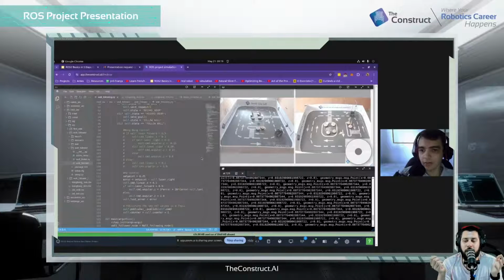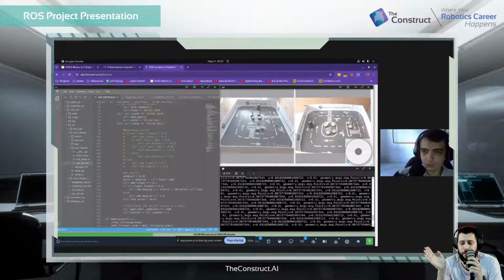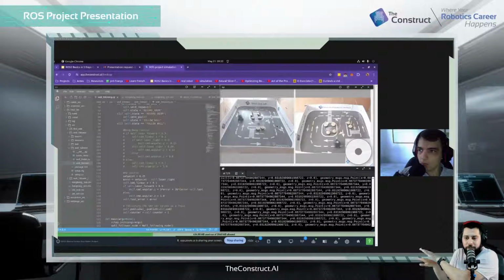Okay, so this system is a very non-linear system. Very small differences in the parameters of the system would generate very different results at the end. Right. For the controller, the set point is the right side of the robot, right? Yes, exactly, just one value, 25 centimeters. The robot should stay 25 centimeters away from the wall on its right. But is that one index you're looking at, or a range of indices of your LiDAR, taking an average? Just one.